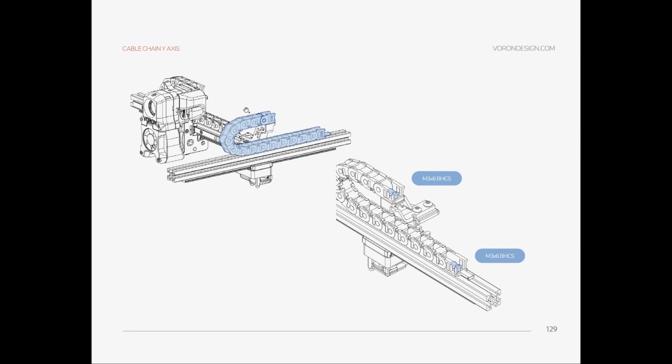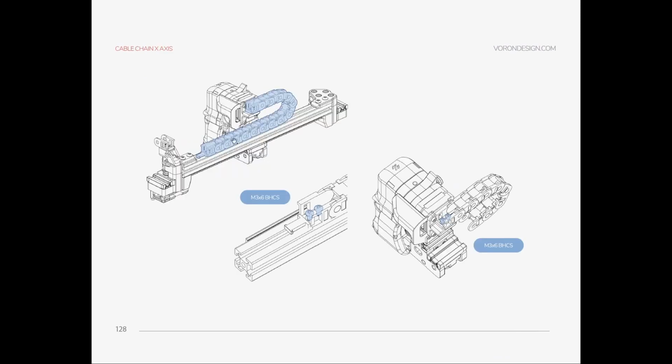And yeah, for your low current wiring, for example, the wiring which is coming from the tool head and going to your electronics chamber. First, you run your cable chains. After that, run wire from the tool head, follow the cable chains and go to the electronics compartment and go to the furthest points, add approximately 30 centimeters and cut your wire. And with this, referencing this one, cut the other wires as much as you need.